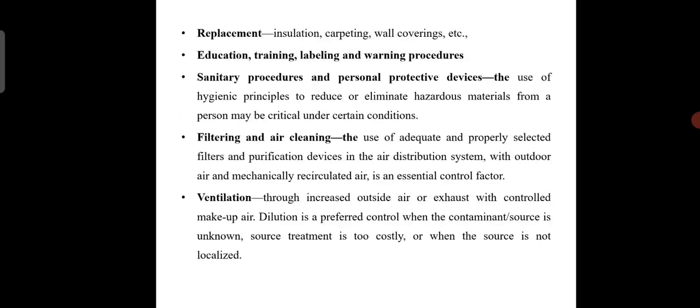And the third one is infiltration. Infiltration is the process by which outdoor air flows into the building through openings, joints and cracks in a wall. This can be achieved by having dry brick walls without any plastering, and we can have filler roof slabs. These will maintain the temperature inside a building and also improve air ventilation through these open joints. And we can establish air cleaners.